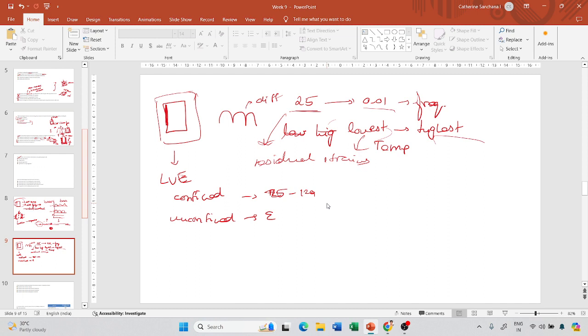If the modulus keeps varying, then the stress required to produce this strain also varies. So what will you do? The equipment has to do a trial run first. Let us say I'm testing at 25 degrees Celsius and 25 hertz. This is the first frequency that I'm going to apply to the material at this 25 degrees Celsius. I have to provide something called a modulus value, say a seed modulus.